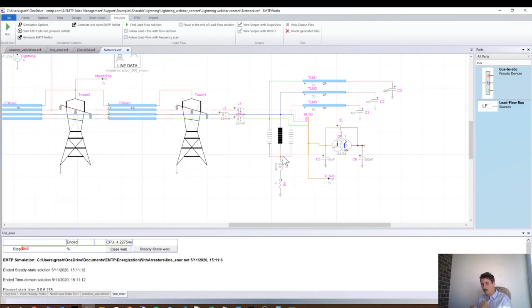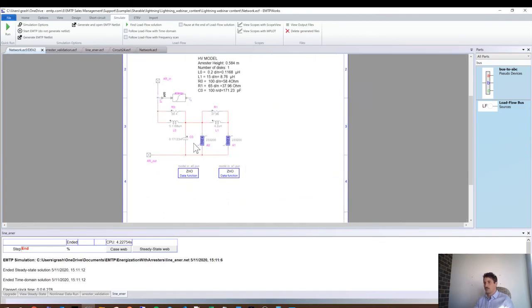When you have a surge arrestor connected to an apparatus, for lightning you should model the conductors in between, because lightning is such a fast phenomenon that you may have voltage differences between 2 given points in the substation. Also, like I explained, the lead wire for the ground wire should be modeled, and the grounding as well. Okay, so if I go inside here, it's this same surge arrestor. You see that we put the small energy meter to monitor the energy.